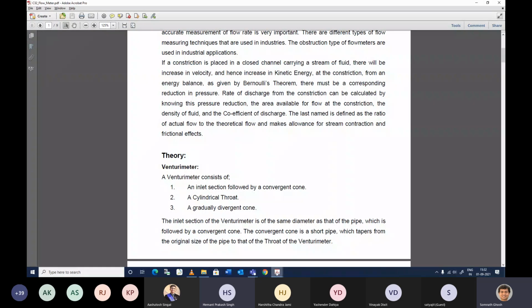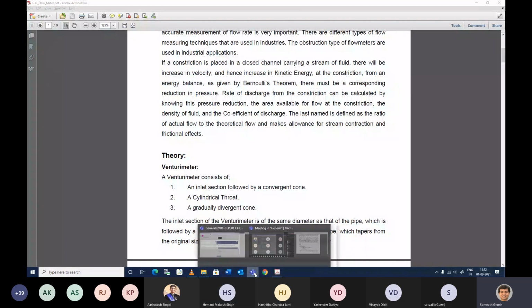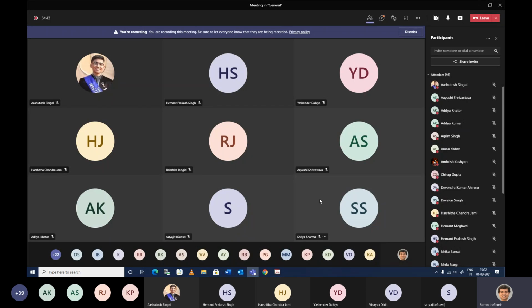Bypass valve? Okay. If you have any uncontrolled flow inside the pipe network, just to avoid any accidents, you need to have a bypass flow. If anything is blocked inside a pipe flow and you have a constant flow coming in, it can generate an enormous pressure inside the pipe circuit.